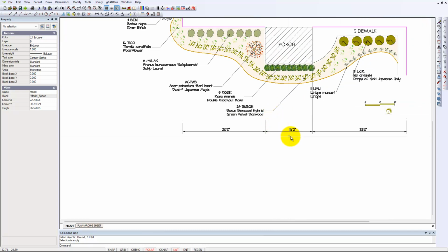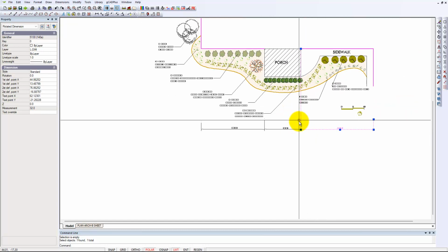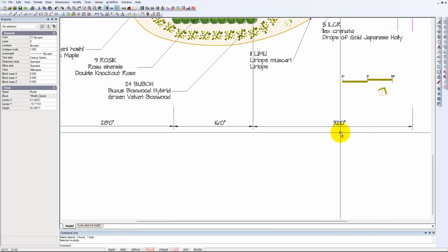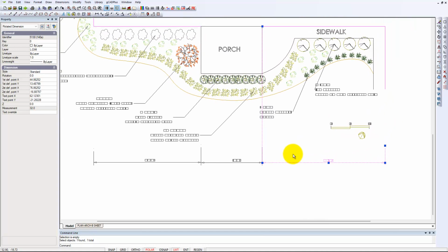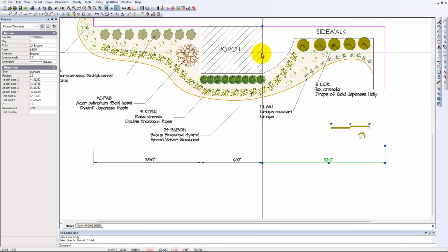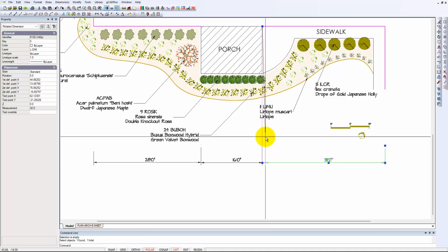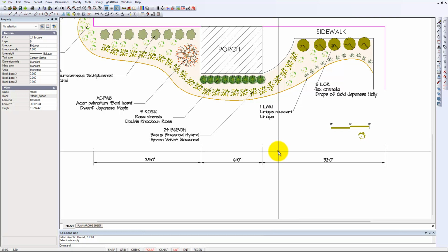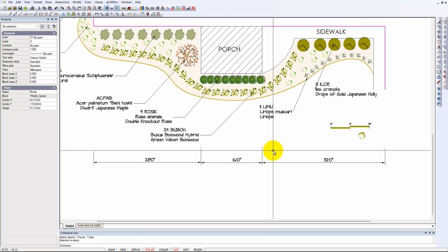So do pay some attention to dimensioning. And here's another example. We'll do it again. We'll check this one, which is 32 feet, no inches. And again, we will grab hold of that grip and move it away and move it down in the vertical. And see how as I'm moving now, you see again that dimension changes. So we can come down and just roughly line up like so. So being careful with your dimensioning, I think, is important.